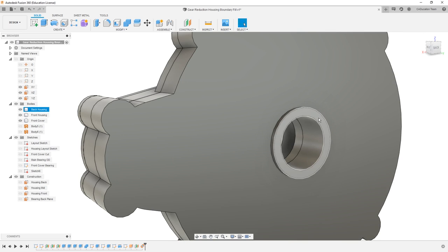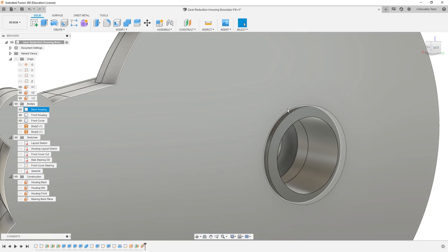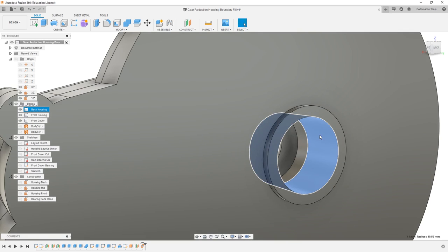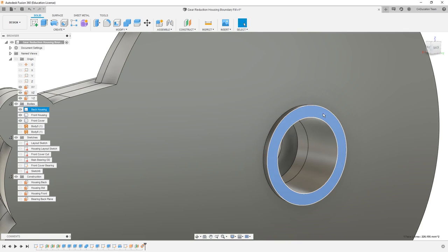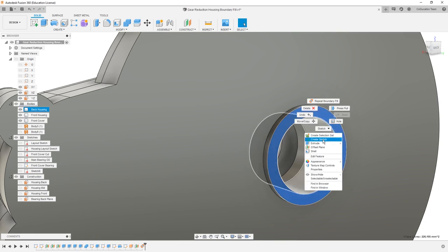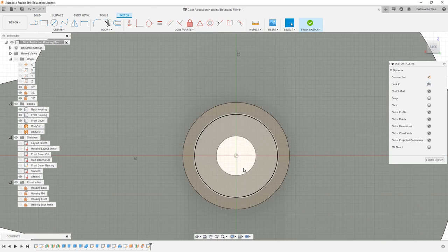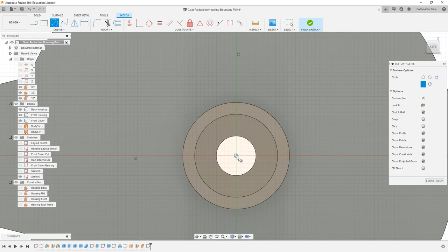We can also simply create another extrude. So in this case, we added 2 millimeters to the back of the housing, which was already 3 millimeters thick. Now remember, this back piece is still solid. We haven't removed all the inside from it yet. But what we can do now is create an extrude on the back of this face by creating a new sketch. And we're going to use C on the keyboard to create that ID.